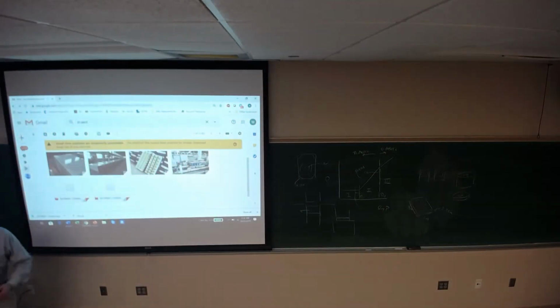So they took a shoe, and what they did was they mimicked the behavior of someone walking, right? And then they introduced a grit. And the grit they introduced was alumina initially. What they were looking for is the wear or abrasion resistance of these tiles, of tile surfaces in the presence of someone walking on them. There's no standard for this, but what they get is that with alumina, everything fails.